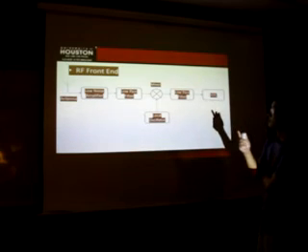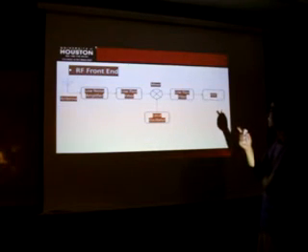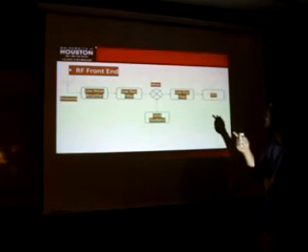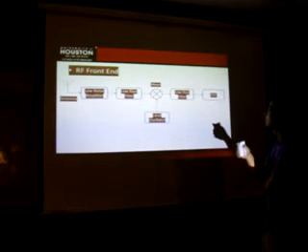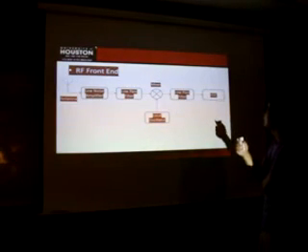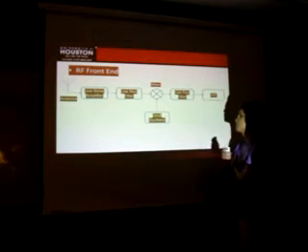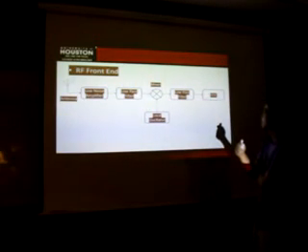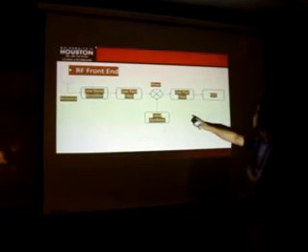Here is the receive path of the RF front end. The signal from the antenna is first sent to the low-noise amplifier. Then it is processed by the low-pass filter. The low-pass filter will filter out some high-frequency noise, and then the local oscillator will down-convert the RF signal to the intermediate frequency signal, and then send it to the low-pass filter.